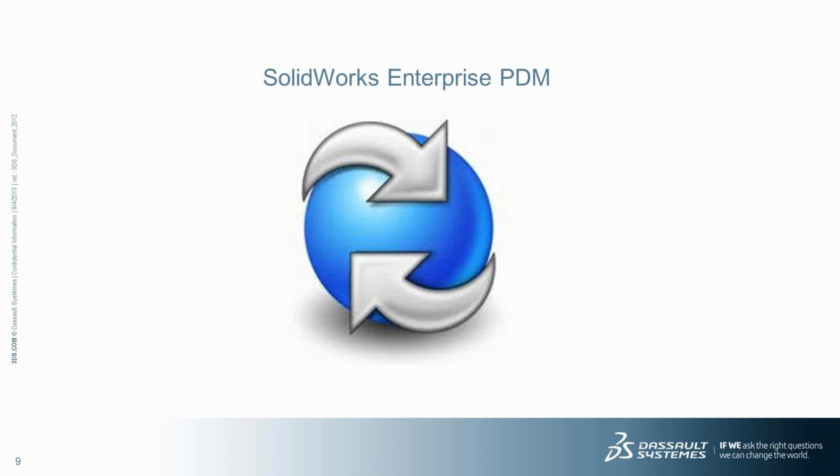Now, the reason I felt this was a good lunch and learn, because not everyone's using PDM yet. I hope someday everyone is. But right now, using the tools in SolidWorks, it's not surprising to me that you have mates blowing up, changes disappearing. Well, changes disappear because the part that you changed is not the one that SolidWorks opened up because it found a duplicate. I challenge you from here forward.